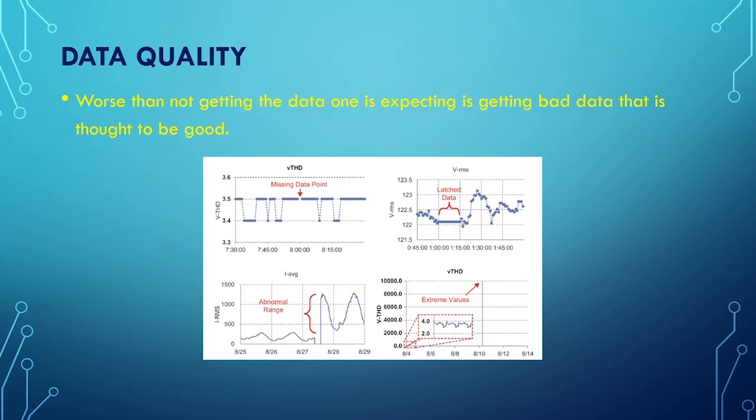As we can see from the figure below, with missing data, a large gap of data is often noticed. However, a small gap in data can easily be missed. Latched data, another often overlooked anomaly, is latched data. Most parameters should have some form of randomness. If consecutive values are giving you the same numbers out to a significant decimal value, it is most likely latched. This can be caused by a malfunction in the processing or communication handling.